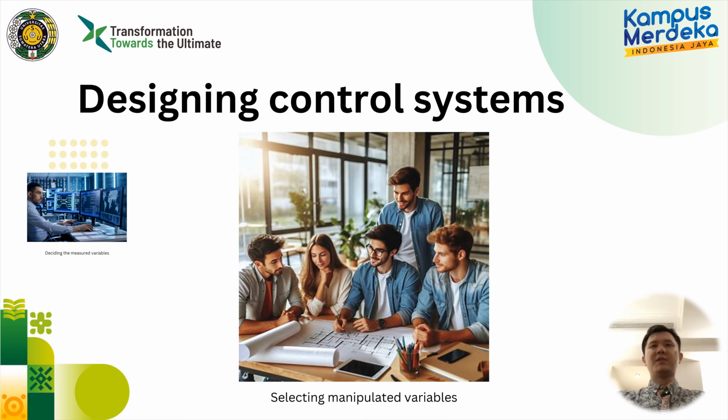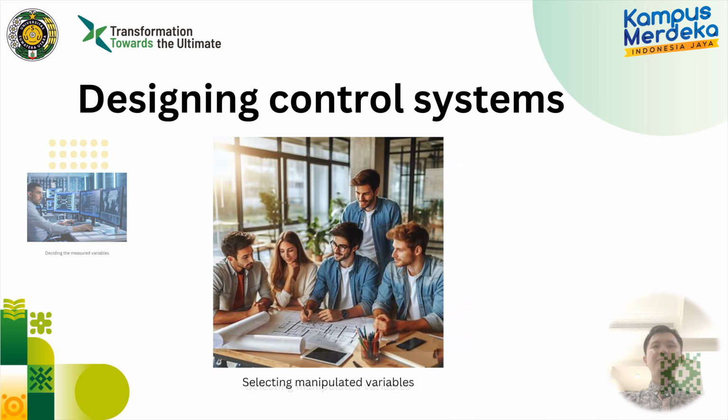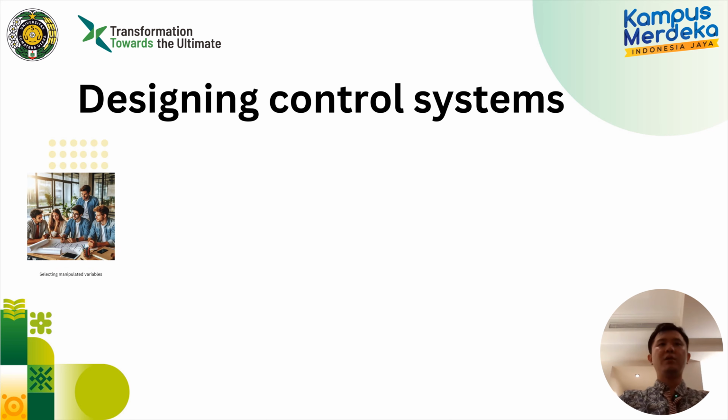Once the control objectives are specified and the measurements are identified, the next question is how we can cause a change in the process. In other words, what are the variables to be manipulated to achieve the control objectives? Usually, we have many options in this selection, and our decision may affect the quality of the process response, that is, the control performance. Control configuration is the information structure used to match the available measurements with the available manipulated variables. Normally, we will have many possible configurations.